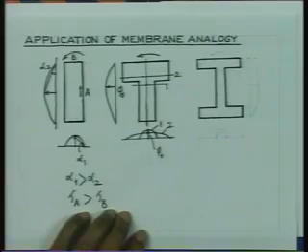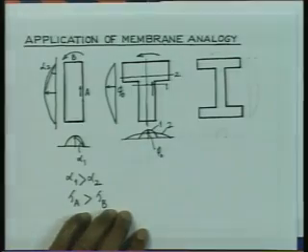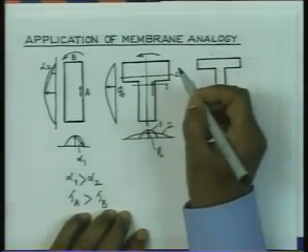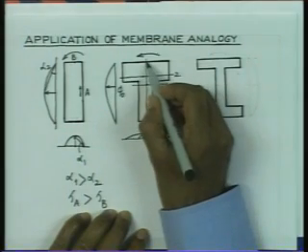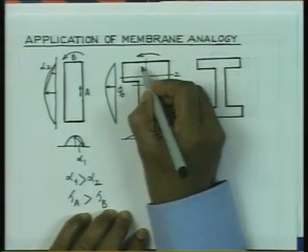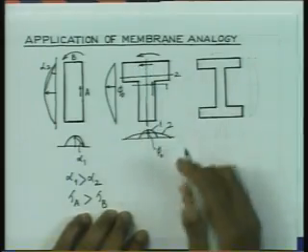And immediately you can decide that the stress is going to be acting like this at this point, and it is highest. And obviously, the stress at this point is lower than the stress at this point, and it is going to act like this. And you will find also the corner stresses are all zeros.